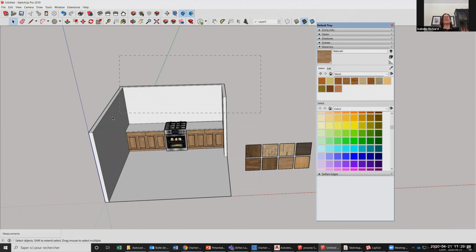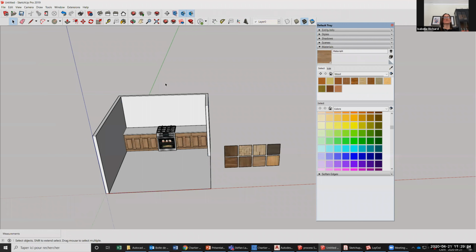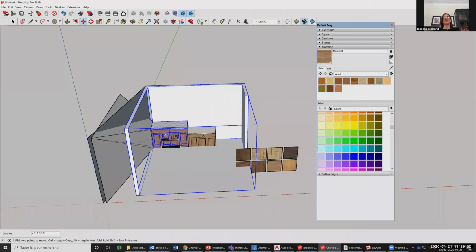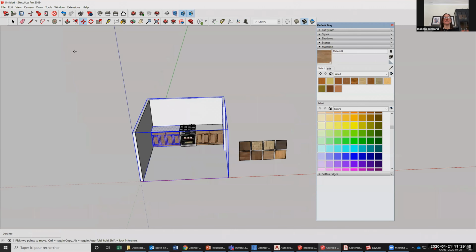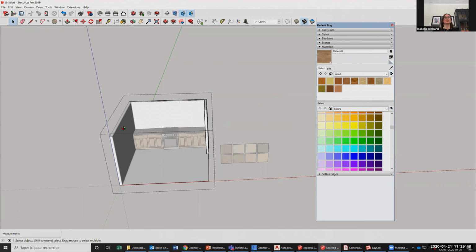Now, my first section here that was not grouped, see there's a part that is still connected to the wall, so I haven't made a perfect group of wall there, so I want to change it. There's always a way to change a group that is already done by double clicking on the group, and now you're inside the group. You can change anything.